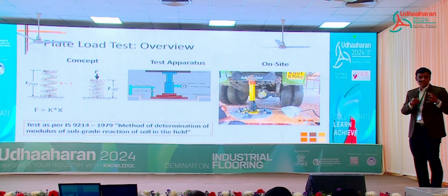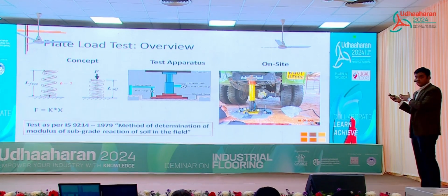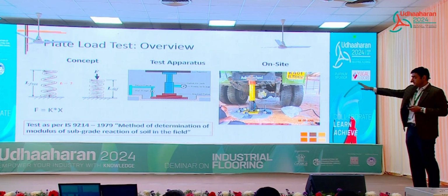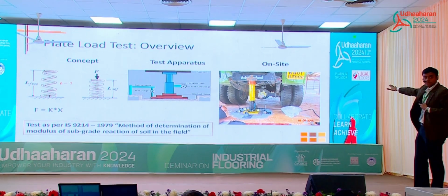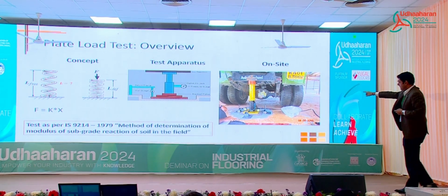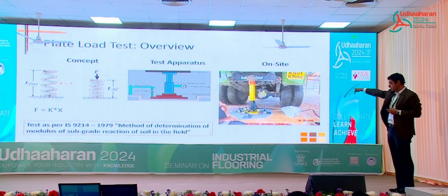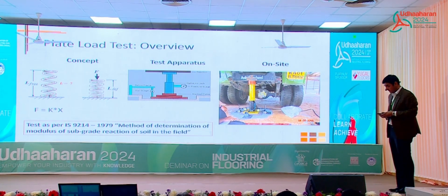Okay, now on the field, how do you know that the soil at your site is a hard mattress or a soft mattress? What you do is a plate load test. This is the most common and most preferred test that we use. So again, visualizing your soil as a spring, this is how the apparatus looks, and this is how it looks on the site. So what we have here is a jack. We have a set of plates, we have a jack, and then we have a counterweight. With that counterweight, we are able to apply force on the earth, and then we note, by applying constant pressure or increasing the pressure or force, how much the earth or the soil is compressing or getting displaced.